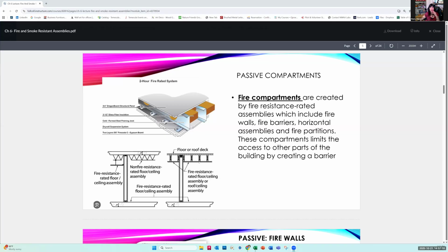So let's say you had this awesome ceiling and you wanted to cut into it to create a recessed tray or something. This is where you need to know that it's a fire rated ceiling roof assembly, and you can't do that. Or you decide that you want to push in some different kind of lighting, and therefore you're creating a penetration, and you need to make sure that you are caulking it with a fire resistant sealant, so you are not spreading the fire. So this is why it matters. Because you deal with ceilings, you hang things up, you design RCPs, so you want to know what's going on in the ceiling as well. You don't want to compromise it. Okay.